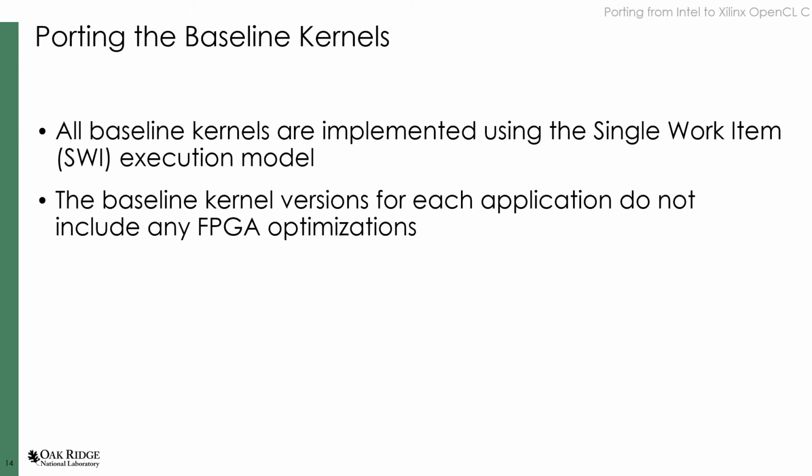The single work item model, in many cases though, is best suited for the resulting FPGA design, as a compute pipeline that accounts for non-trivial dependencies between iterations and that is specific to the kernel specification can be constructed. In the baseline versions of each kernel, there are no FPGA-specific optimizations within the kernel specification. This is helpful in two ways. First, it makes porting the baseline kernels to the Xilinx platform trivial since no optimizations need to be ported. Second, the resulting FPGA hardware synthesized from these kernels serves as the baseline to the FPGA designs that will result from porting the most performant versions of each kernel.